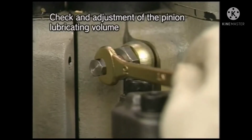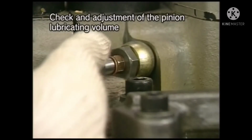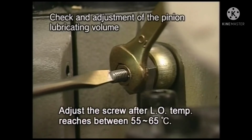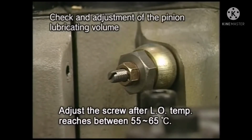If the feeding volume of lube oil does not meet the specified value, first remove the cap nut of the lube oil flow rate regulating valve, loosen the lock nut, and then screw in the lube oil flow rate adjusting screw until becoming fully firm.